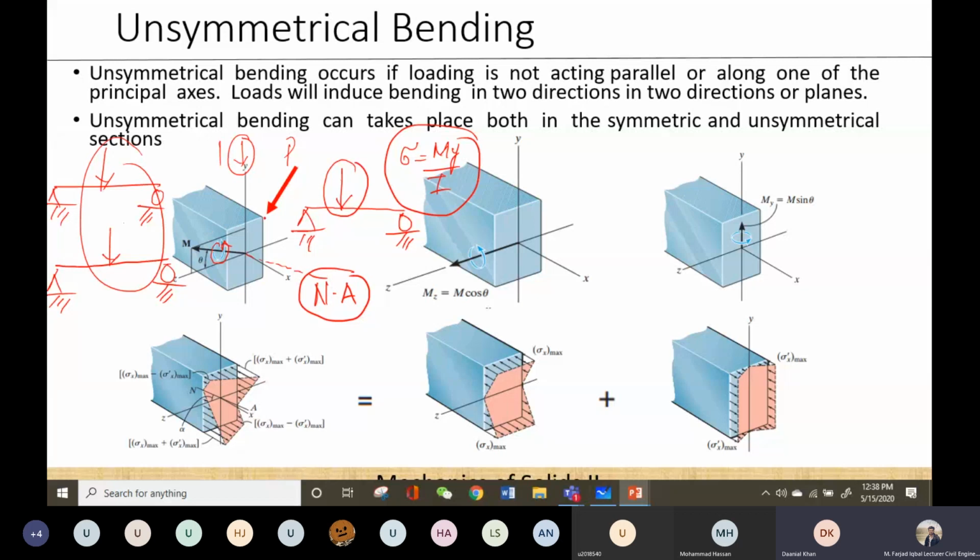But it is dividing like this, you are saying. Yes sir, it is dividing, but like I said, there can be numerous planes passing through the section, but you have to calculate two things. The product moment of area, that should be 0, and the second moment of area, that should be maximum and minimum. So around this axis, it is quite possible that these two conditions won't be satisfied. There will be only two planes around which these conditions are satisfied, and those are basically our principal planes.